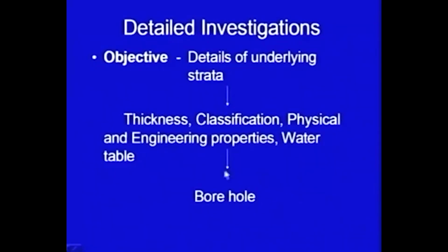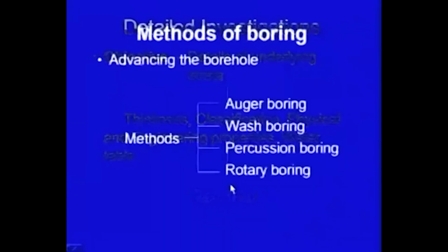The bores are advanced and this investigation is done through boreholes. There are several methods of advancing the boreholes. First method is auger boring, wash boring, then percussion boring and rotary boring.